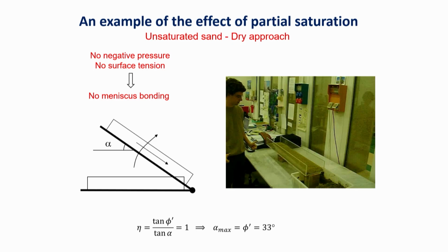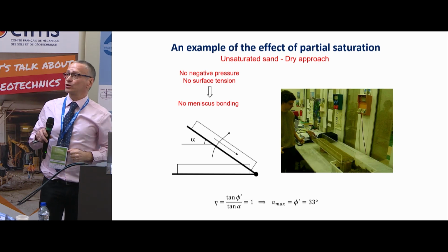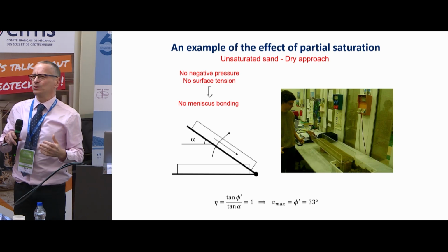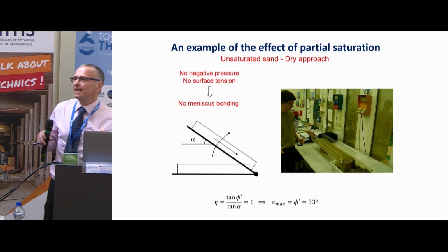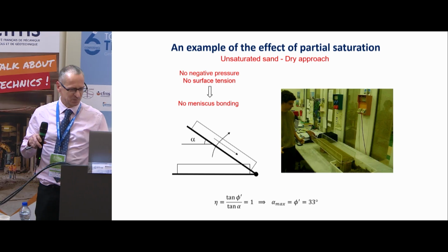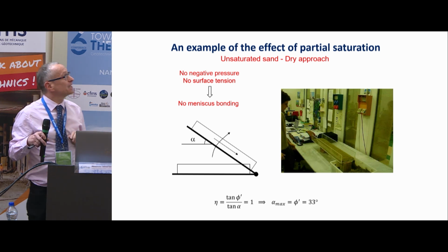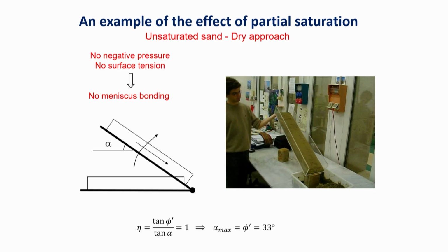First of all, if you were designing it with the dry approach, you would say at 33 degrees it should fail. Okay, but we know that it should stay higher, right? So if I'm telling you that you can incline a bit more, you're not going to be surprised. But you're going to be surprised by how much we can incline that slide